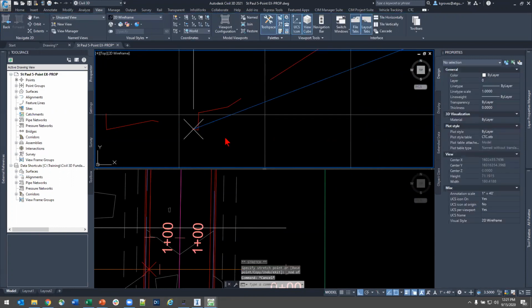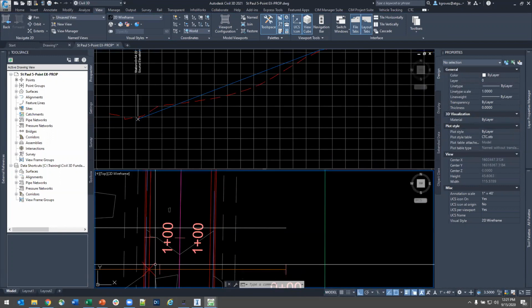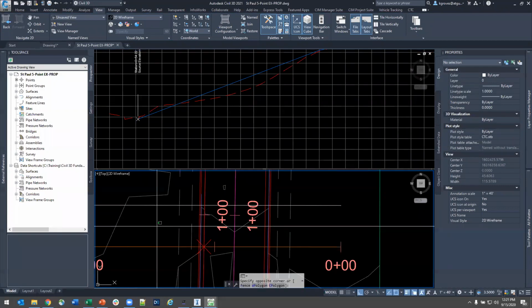So this is how I can make sure, at any point during my workflow, that my two profiles have been locked. Now, this COGO point is not dynamic. Don't expect it to be. If the source profile you're trying to tie into changes, recreate the COGO point and reproject it.